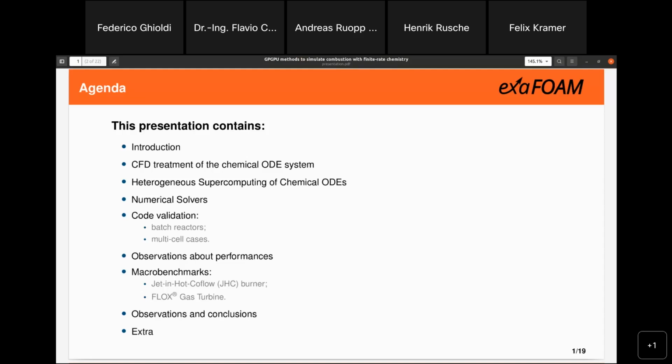I will then move to the CFD treatment of the chemical system, meaning how specifically OpenFOAM handles finite rate chemistry, in particular the ordinary differential equations, which are additional to the usual equations that you have because of the fluid dynamics.